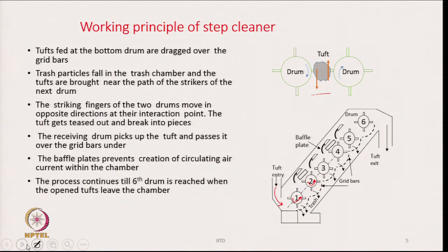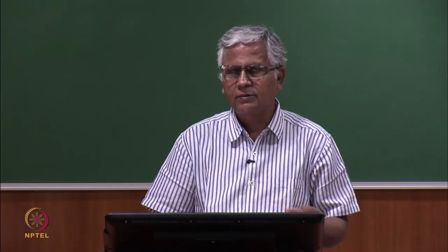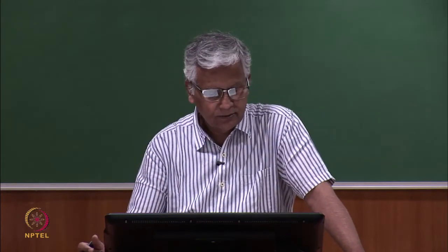The process continues, and the tufts move from drum 1 to drum 2, drum 2 to drum 3, drum 4, drum 5 and drum 6. Gradually it is moving up and up. That means, I am forcing the tufts to move against gravity. So, naturally heavier tufts will take more time to move up, lighter tufts will move fast, and therefore, heavier tufts will be treated more in comparison to the lighter ones.